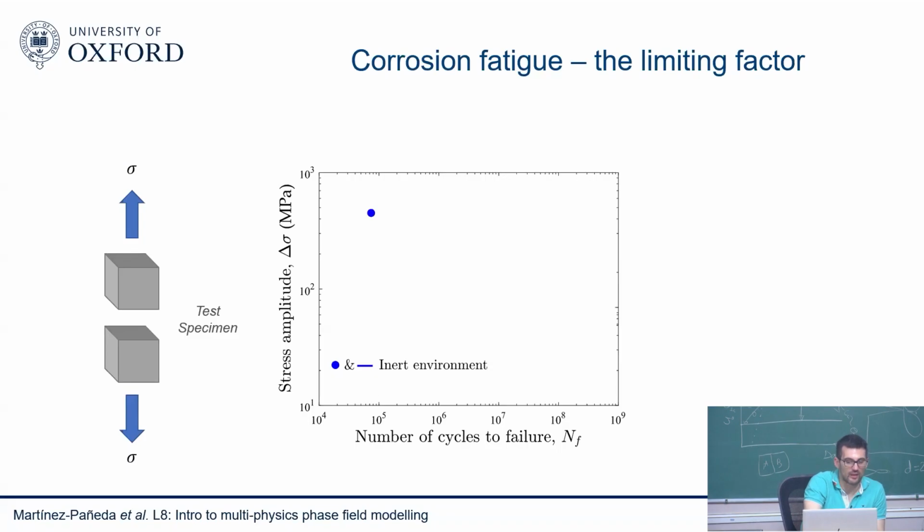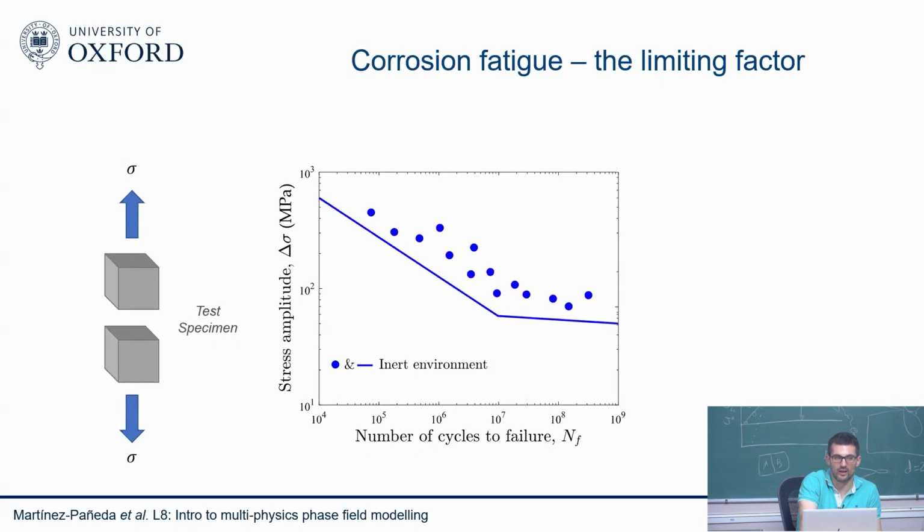So for a given stress amplitude that they measure, they get a number of cycles to failure, exactly as we discussed in the first lecture. Then they change the stress amplitude, they lower the load a bit, failure happens a bit later, again, and after a number of experiments, you get enough data points to make an SN curve. You make sure your SN curve is conservative, below the data points, but once you get the SN curve, that's all you need.